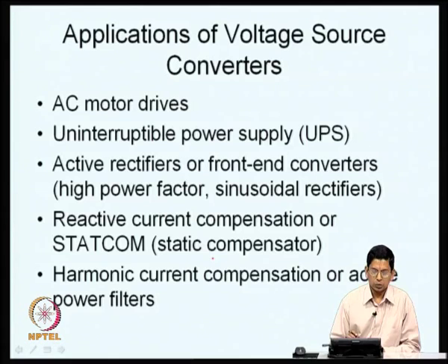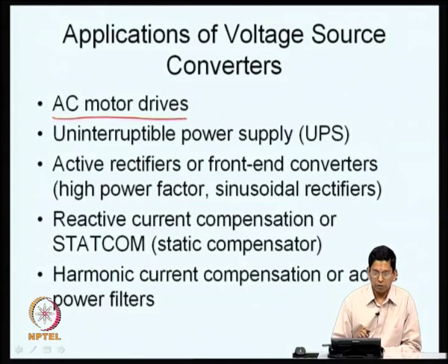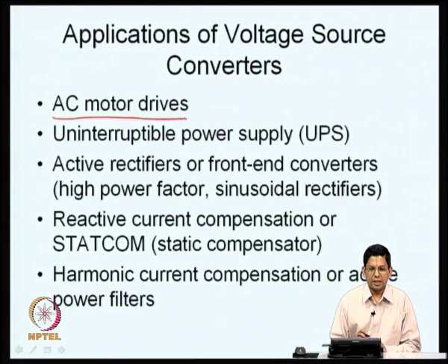So, what all you can do with a voltage source converter is the question. One application is the AC motor drive. You have various motors, such as induction motors, which are very rugged, and you try to control the speed of an induction motor by using an inverter.